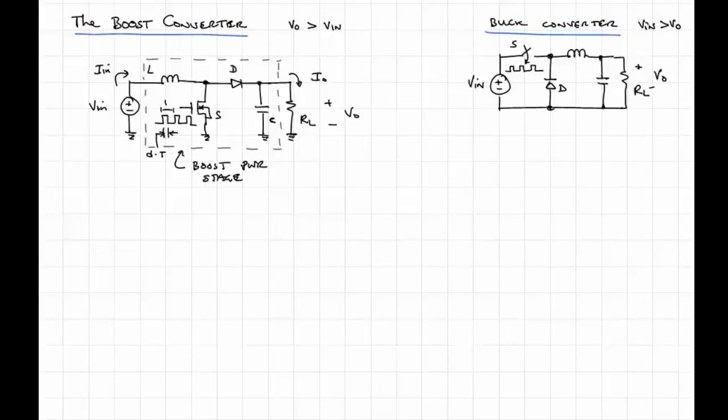You feed the output voltage back to a circuit that compares it to the desired voltage, and then there's circuitry that will make recommendations or changes to the pulse train going to the transistor. Mainly it will change the duty cycle, either increasing or decreasing based on whether you have too little or too much voltage in the output.